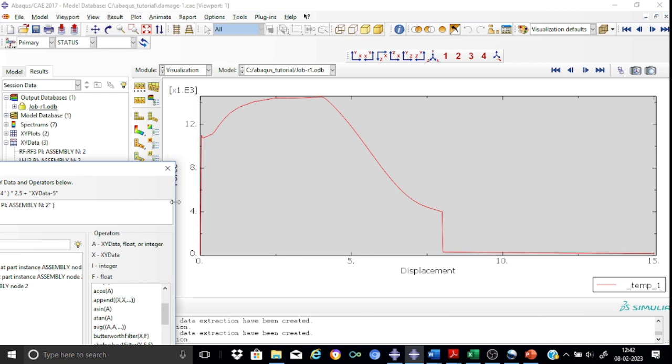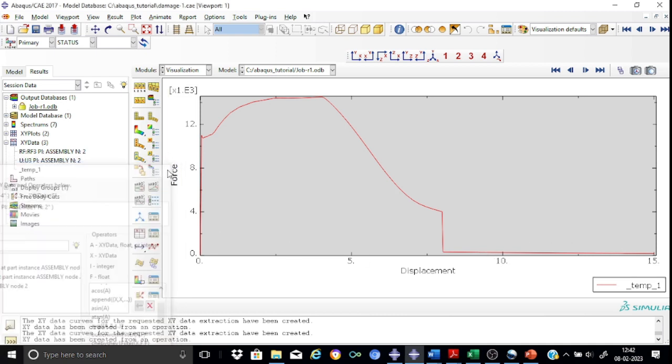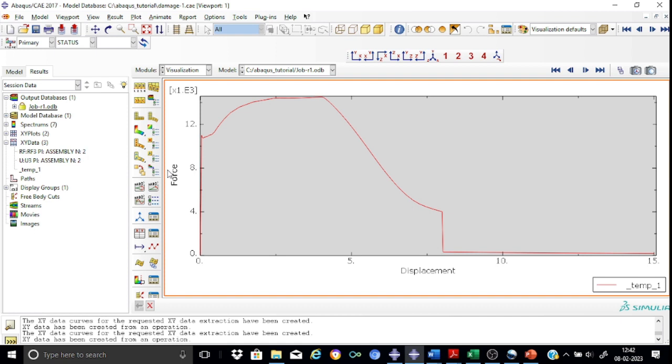So this is how you should analyze the capacity of any component, and this kind of damage analysis is very useful, especially in structural steel as well as reinforced or composite steel-concrete connections, wherein we are able to visualize the damage in the local components, and we can very well tell whether the capacity of this particular joint configuration is governed by a particular component, and the decisive rotation or the capacity level of that particular component or connection.